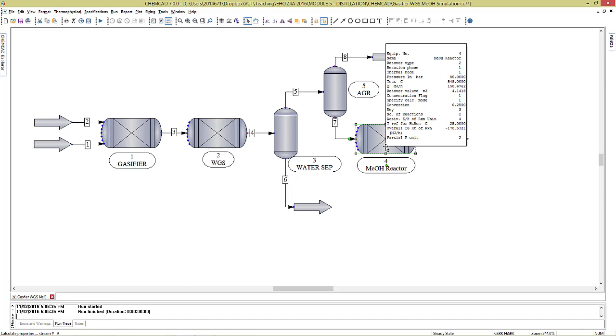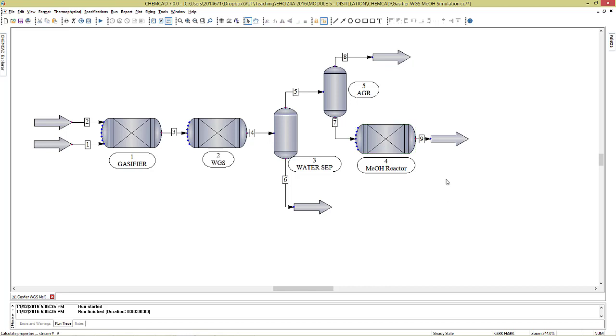does not make sense when you look at it physically. It does not make sense. You end up with a reactor, maybe say you have a 5-meter diameter and then a 25-kilometer length. That does not make sense. So you have to make sure that the conversion that you're getting and the size of the reactor do make physical sense. Once that is done, then I think your simulation up to this point is satisfactory.